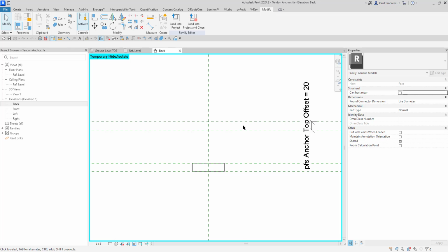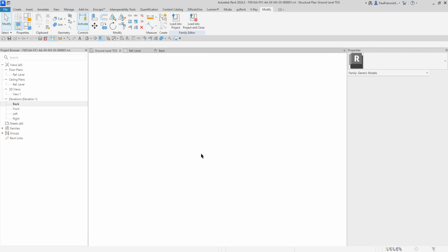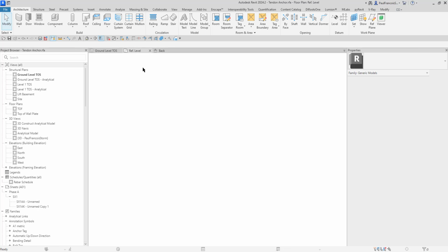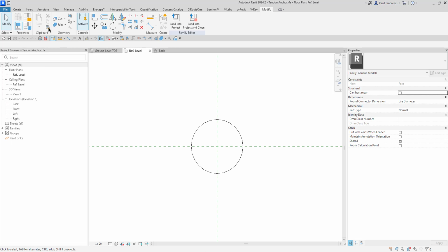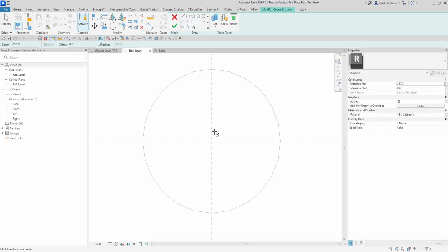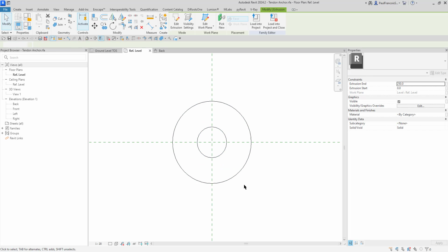At the top, I'm going to go with a, say, 20 millimeter. There, it's also relatively easy. Same command. Go to the top view. Sorry, that's the project. Let me just go back to the family. Go to the top view of the family. Create another extrusion. Again, it's a circle. And it's just going to have a smaller diameter over here. We're going to say that this thing has a diameter, say, of 15. So, accept. So it's quite a thick cable there.